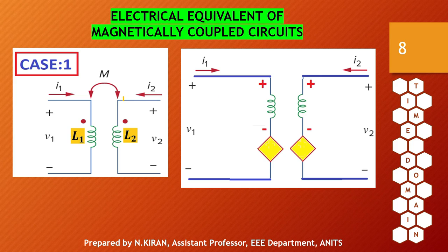Here the polarity of self-induced EMF entirely depends upon the current direction. So here every coil will have two ends. As you can see, I1 current is entering at this terminal of the first coil. That is why that top terminal of the first coil is indicated as positive and the below terminal of the first coil is indicated as negative.